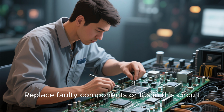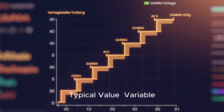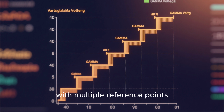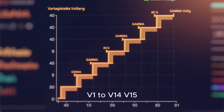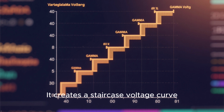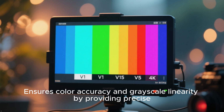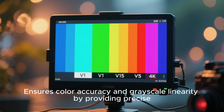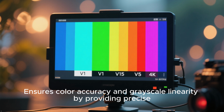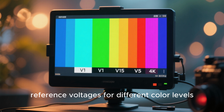Replace faulty components or ICs in this circuit. 8. Gamma voltage. Typical value, variable with multiple reference points V12, V14, V15. It creates a staircase voltage curve. Function: ensures color accuracy and grayscale linearity by providing precise reference voltages for different color levels.